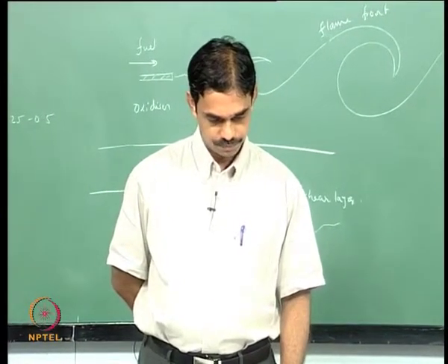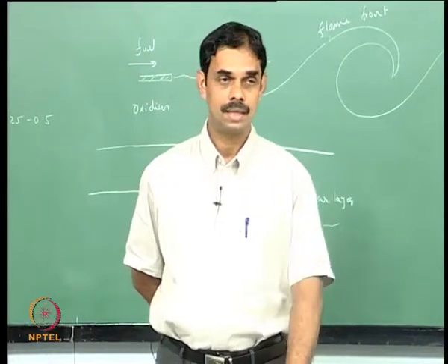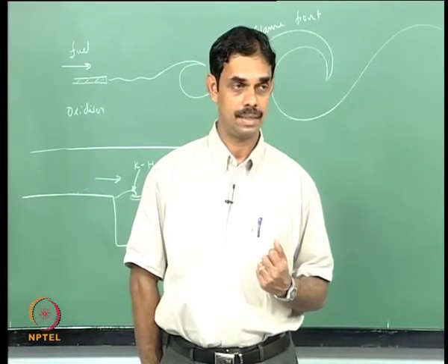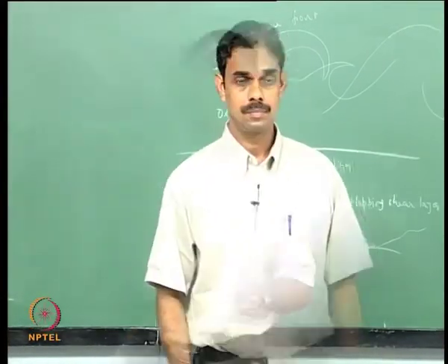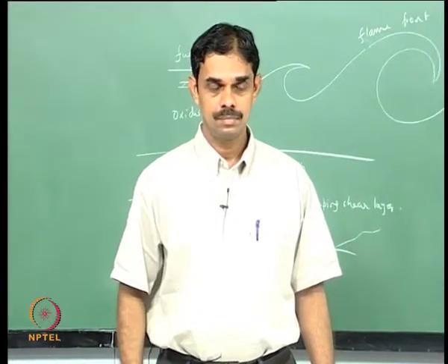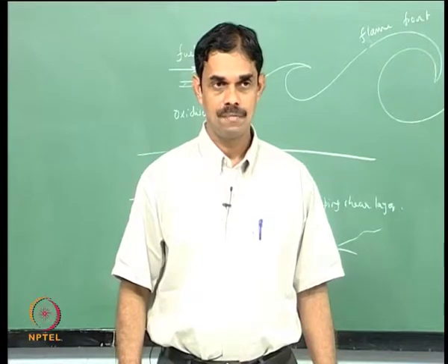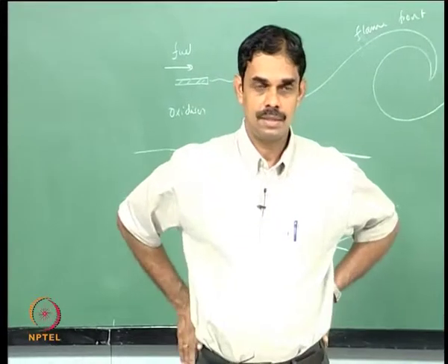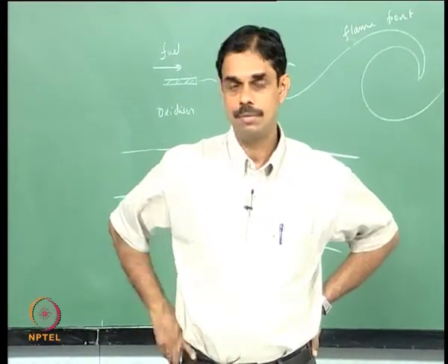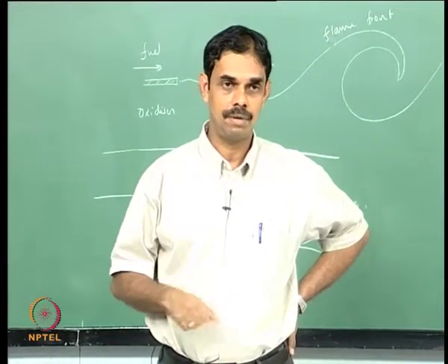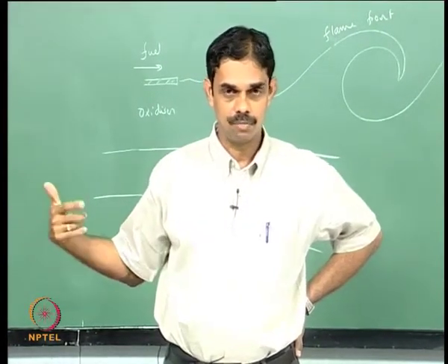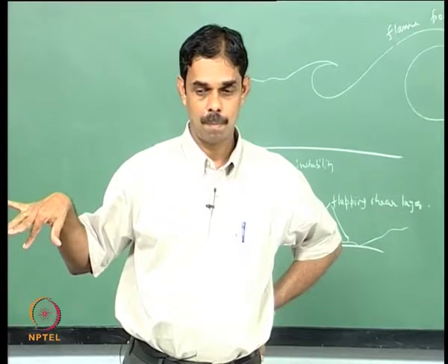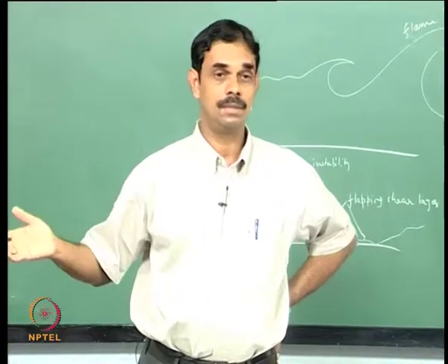Now I want to talk about another instability, another example where vortex shedding can cause some kind of instability, like aerodynamic instability, but happens in combustors, in solid rocket motors. Is it an external agent that is creating an acoustic field, or is it the combustion itself that creates the field? In these cases the acoustic itself is not strong enough to create a feedback, but you will have sound. If you put a microphone you will measure it, but it will not be strong enough to create a feedback. But in these examples, the vortices just modulate the flame, and that causes the periodicity.